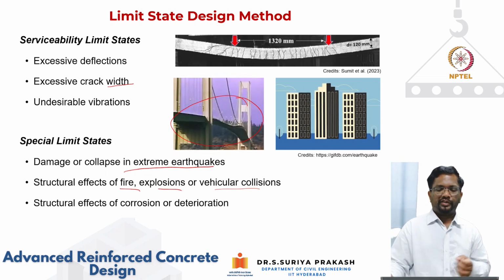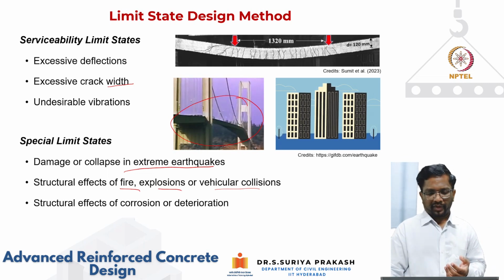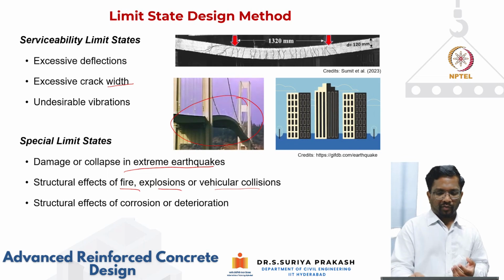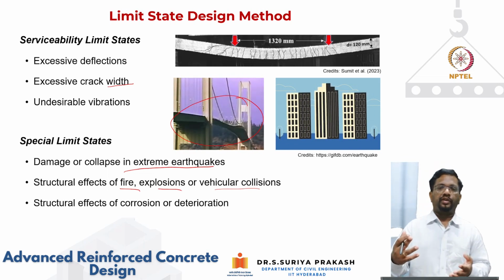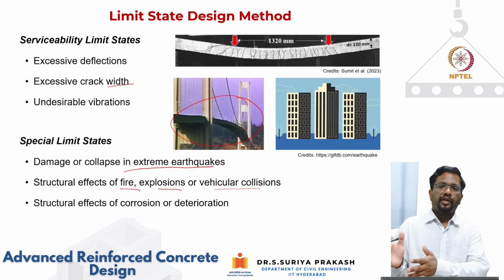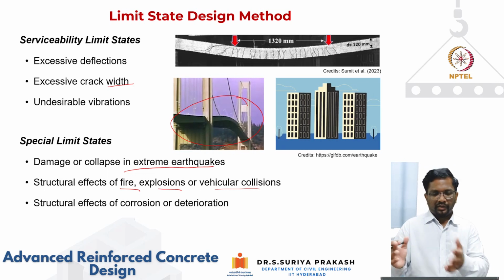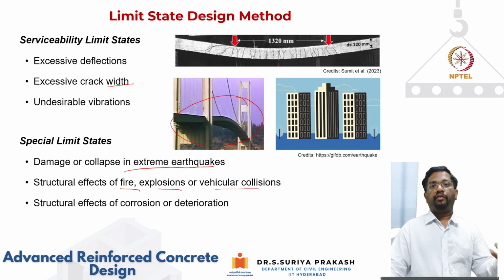But usually we check for the limit state of collapse and the limit state of serviceability. As I've told you, for a water tank, the crack width check will be more important than the strength requirement. In fact, your design will be controlled by crack width rather than strength. So, depending upon what type of structure you're designing, the limit state will govern the design.